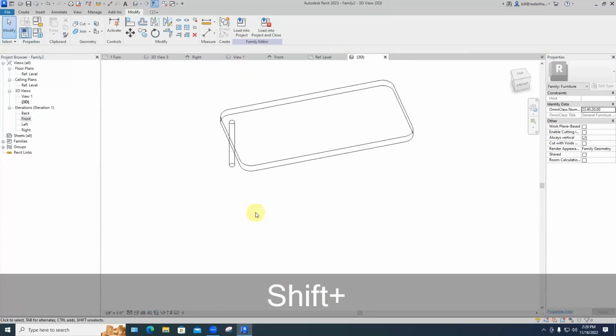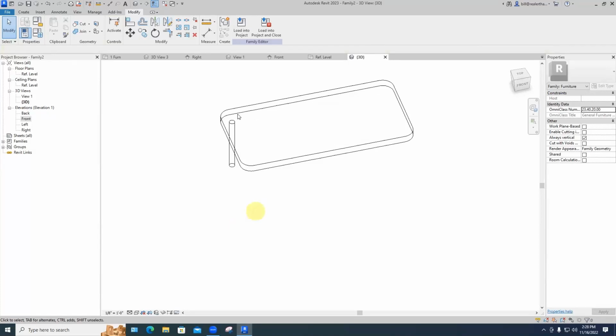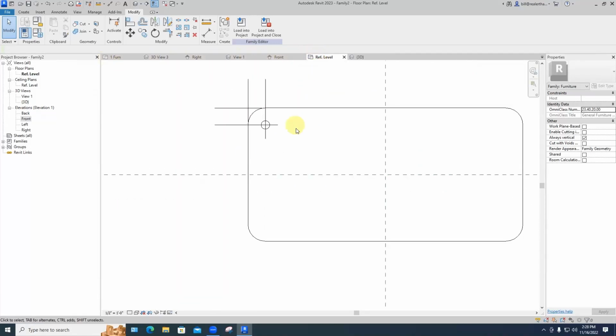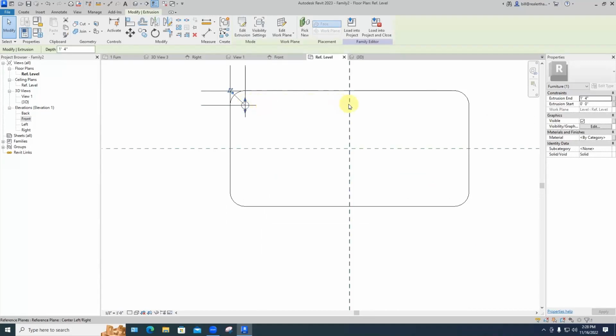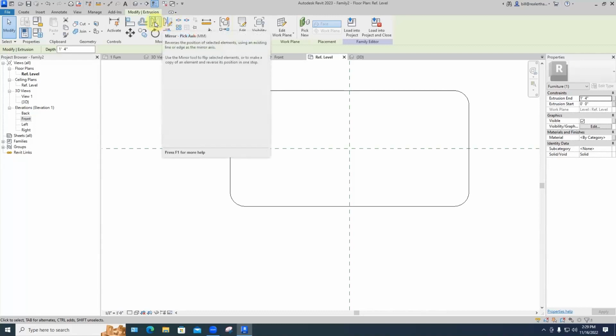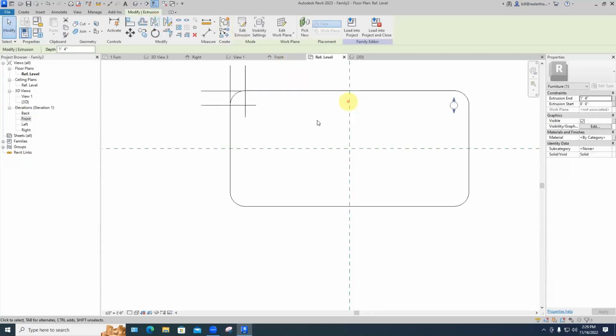It's kind of a pain to go through all that offsetting and measuring and diametering stuff. If we go back into our floor plan view, and if I select this leg, we can simply mirror it about this center axis to get it placed over here. And that's another really good reason to have everything have some sort of symmetry to it, centered on these axes, because these make it very easy to deal with stuff. I'll pick that. We have these two ways to mirror things. One, if there's an existing line, we can just pick the green one. Just pick it, and there's that.